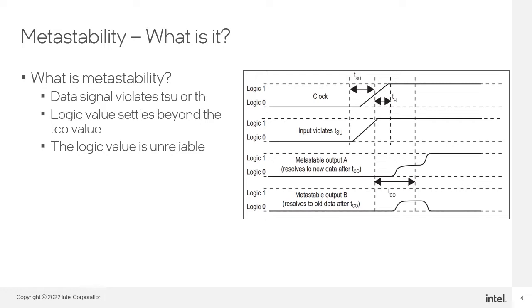Failure can occur when the time it takes to reach a stable state of 1 or 0 exceeds the allotted time, which is the register's clock-to-out, plus any timing slack in the path from the register. When a metastable signal does not resolve in the allotted time, a logic failure can result if the destination logic observes inconsistent logic states.